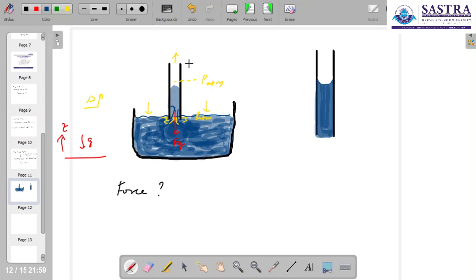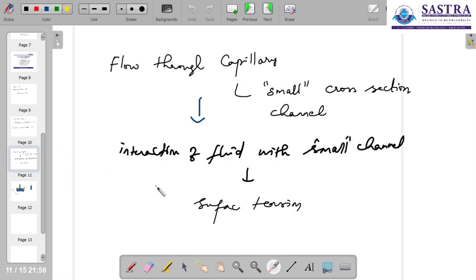Now if we zoom into this part, I have slightly increased the size, one can easily observe that there is actually a curvature of the fluid layer. This curvature is what is predicted by the Young's Laplace equation, or using the concept of surface tension that we have seen in the earlier videos. A fluid surface always tries to minimize the surface energy per unit volume.